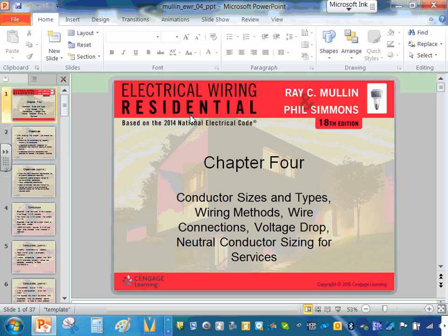So here's your panel right here. They take a bunch of conduits out of this panel all the way to boxes in the ceiling. They bring a bunch of conduits to the box from right here, right? And from there, they use cables to tie all this equipment to the circuit that's coming in. They will bring 8 circuits inside this 3/4 inch conduit into a bigger box like this. Now we have 8 circuits sitting in that box.